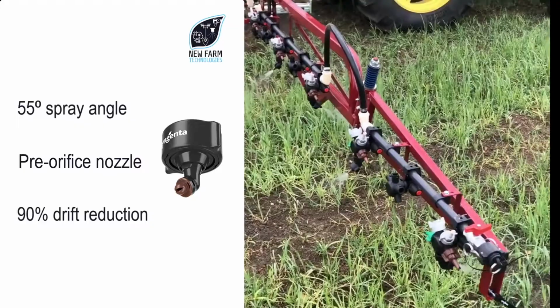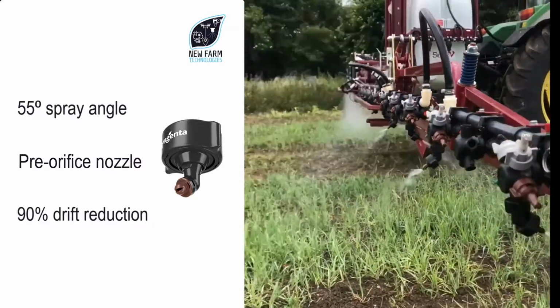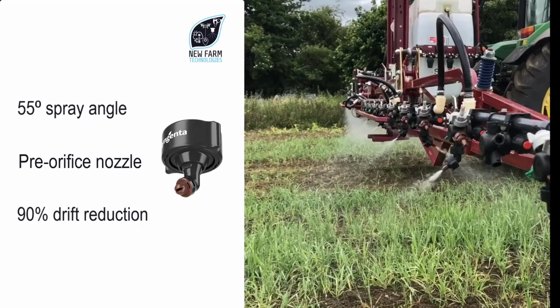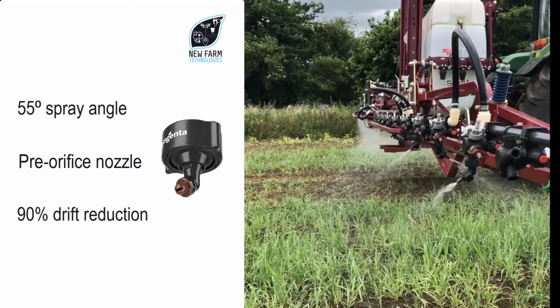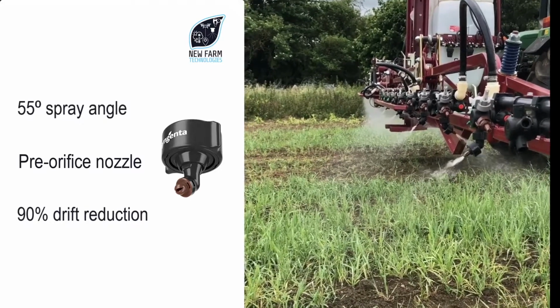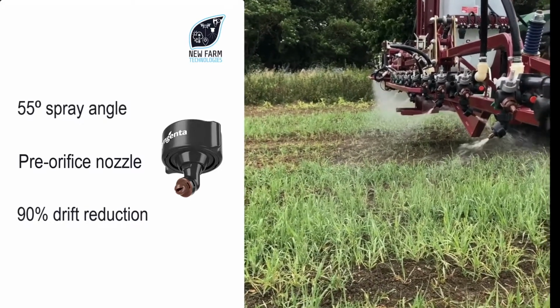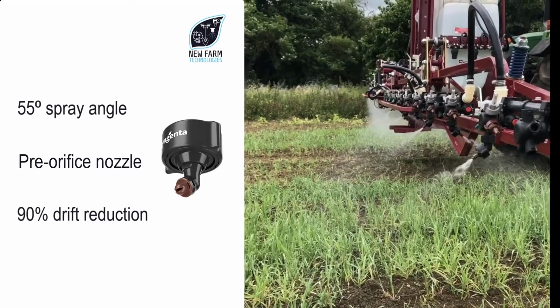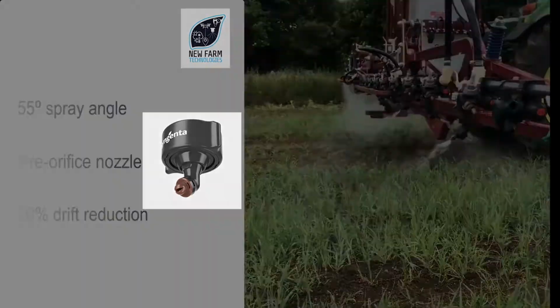And here you can see the fantastic pattern of the 3D90 across the boom in comparison to the flat fan nozzle. And on the far side, flat fan, near side, 55-degree 3D90, minimal drift, maximum deposition, and a lovely example of not compromising too much on drift whilst maximising efficacy.